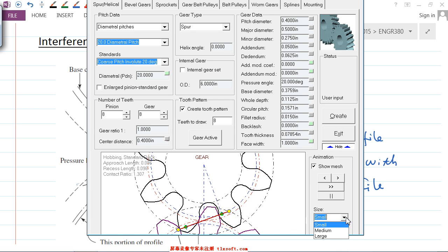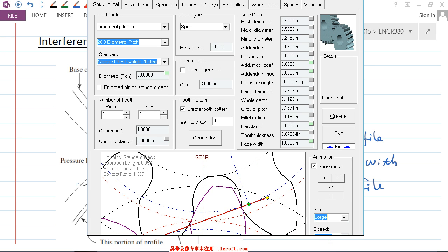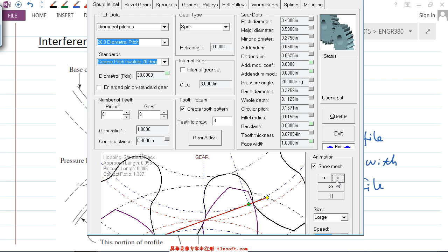Let's give it a little bigger here. Oh, there we go. This portion, this is involute, right? This is involute. But what about this from here to the bottom, this base circle here, from here to here? Remember what this is, this portion. This is not involute. This is actually what? We use a straight line, right? This straight line.